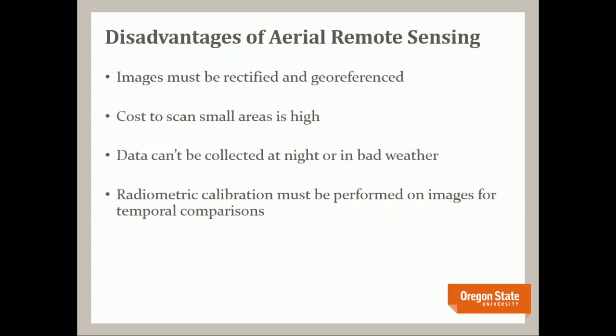Disadvantages of aerial remote sensing: the image must be rectified and georeferenced. Cost to scan a small area is high. Data cannot be collected at night or in bad weather. Radiometric calibration must be performed on the image for temporal comparison.